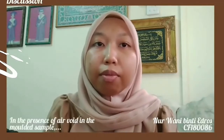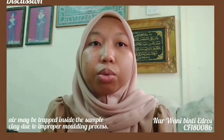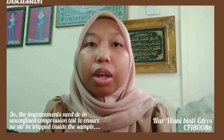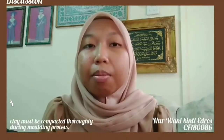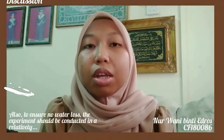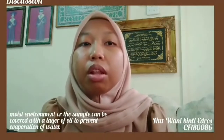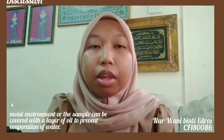In the presence of air void in the molded sample, air may be trapped inside the sample clay due to improper molding process. This may result in lower unconfined compression stress. So, for improvement in the unconfined compression test, we need to ensure no air is trapped inside the sample. Clay must be compacted thoroughly during the molding process, also to ensure no water loss. The experiment should be conducted in a relatively moist environment, or the sample can be covered with a layer of oil to prevent evaporation of water.